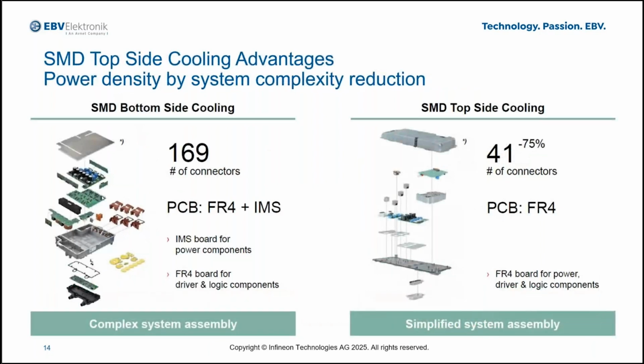This translates into what we can see here: a much simpler system assembly when you can put SMD topside cooling devices in your design. These are real life examples where you reduce the number of connectors and simplify the PCB. In the end, you bring a lot of advantages at system level.